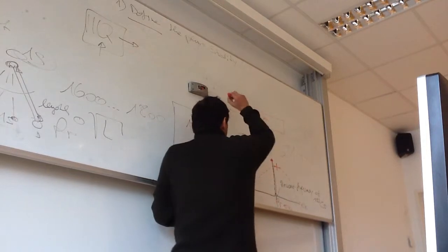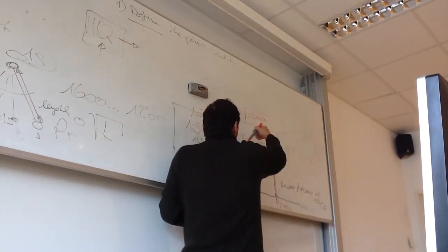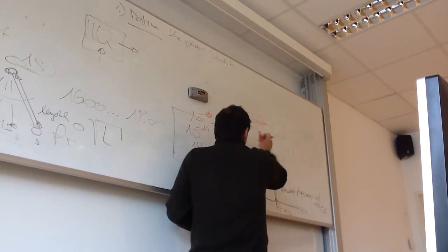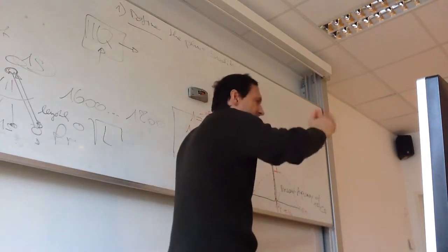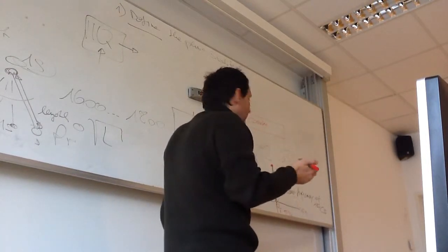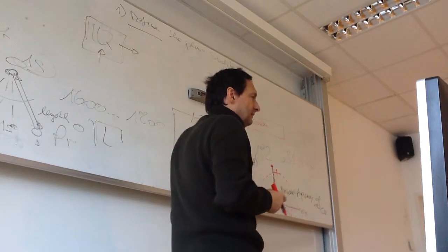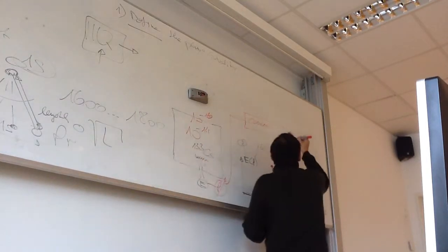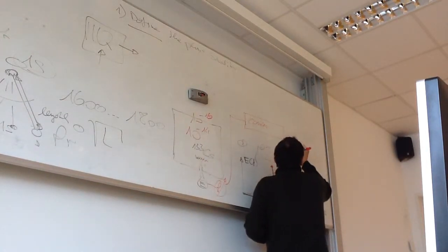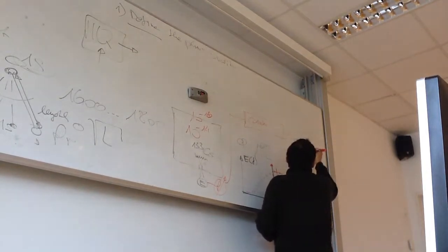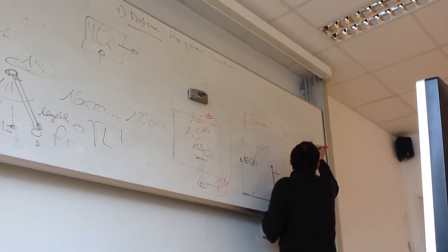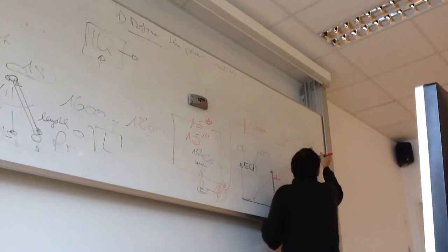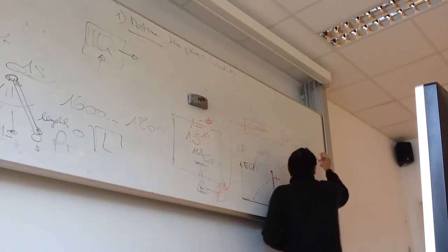And this you will send to a counter. And if the counter exceeds that number, then it rolls over again to 0, and that's 1 second. So this counter counts up from 1, 2, 3 until that number. And here it rolls over and starts again.